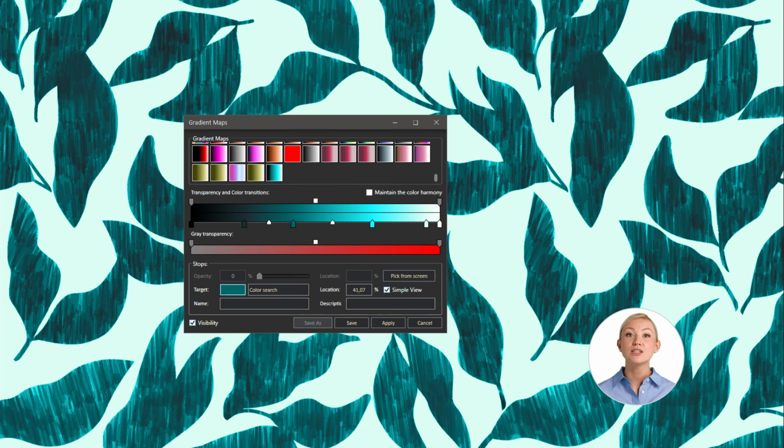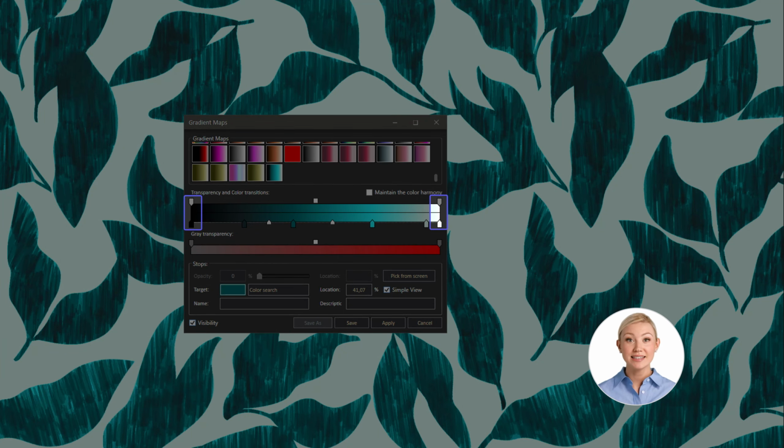by moving the thumbnails on the Transparency and Colors bar that appears below, and we can adjust the effect of the chosen colors on the saturated areas from the gray Transparency bar as well. We can also adjust the opacity of the colors from the opacity parameter below. When you add Gradient Map Effect, black and white colors are always selected automatically. If there are no black or white colors in your design, you can delete these colors by right-clicking their thumbnail on the Transparency and Colors bar.